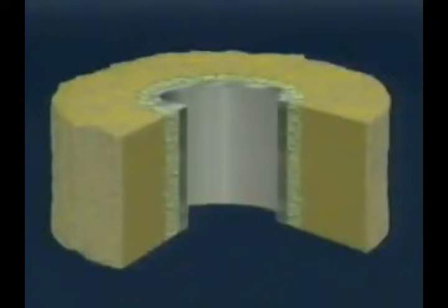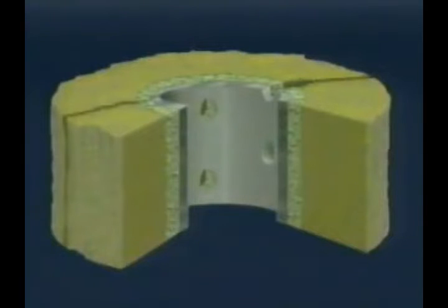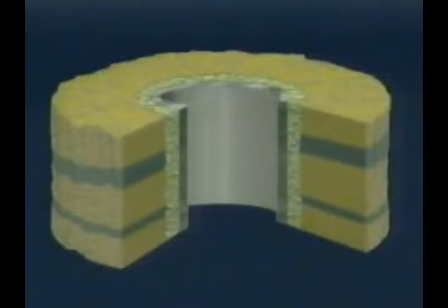Perforating prior to fracturing is typically done with conventional casing guns and positive pressure. Phasing of the perforations may increase the likelihood that the perforations will come close to aligning with the azimuth of formation fracture. When several zones must be fractured, limited entry fracturing is sometimes employed. In this technique, the perforation diameter and number are limited in order to maintain a high bottom hole pressure and break down successive zones.